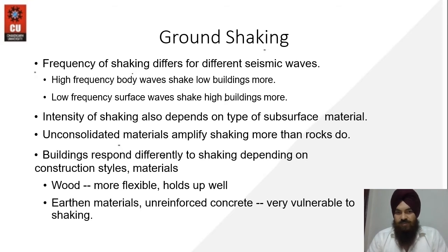earthquake is low. Then the intensity of shaking depends on the type of subsurface material. Subsurface means the material on which the foundation is resting. That can be a hard strata or a loose strata. We have already discussed it. It will depend upon the subsurface material. For loose strata, the intensity of shaking will be more. For hard strata, the rock-type strata beneath the structure, the intensity of shaking will be less.